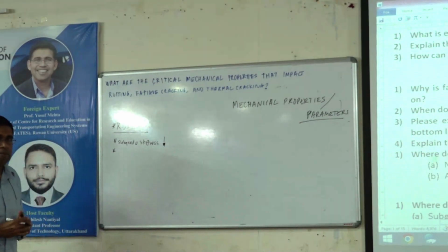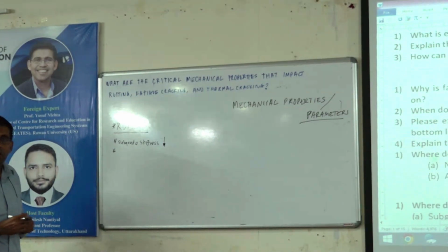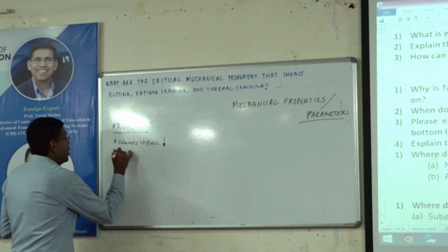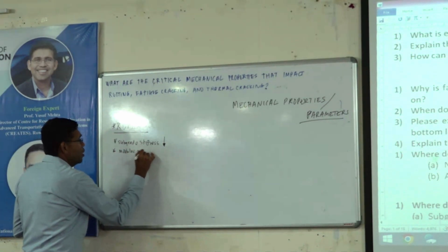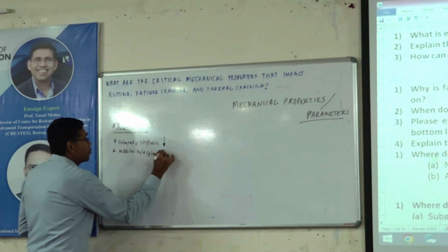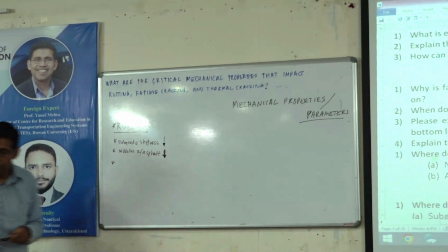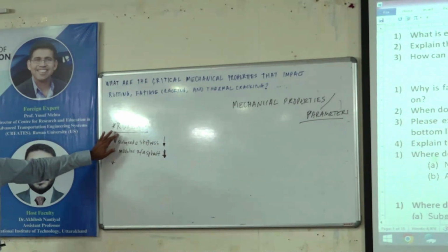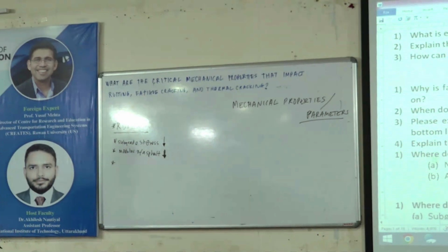Modulus of asphalt. Okay, that's good. So modulus of asphalt is low. That could happen, right? So you have a low E value of asphalt at that temperature. At what temperature does rutting happen? Higher, 30, 40, 50 Celsius or greater, right? Modulus of asphalt.